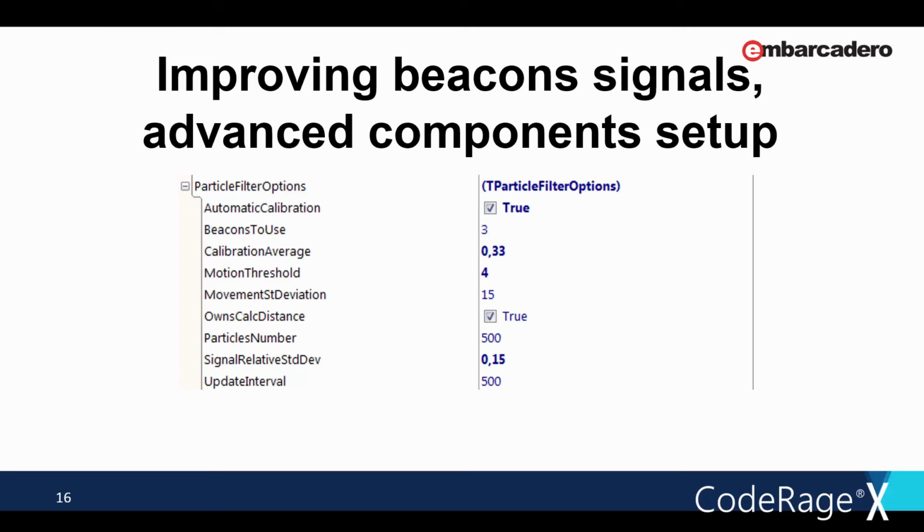Beacons to use: the number of beacons to be used in the indoor positioning system. In scenarios like a corridor and rooms, 3 or 4 beacons will be enough, while in big and empty scenarios you will increase the number to 6 or 8.